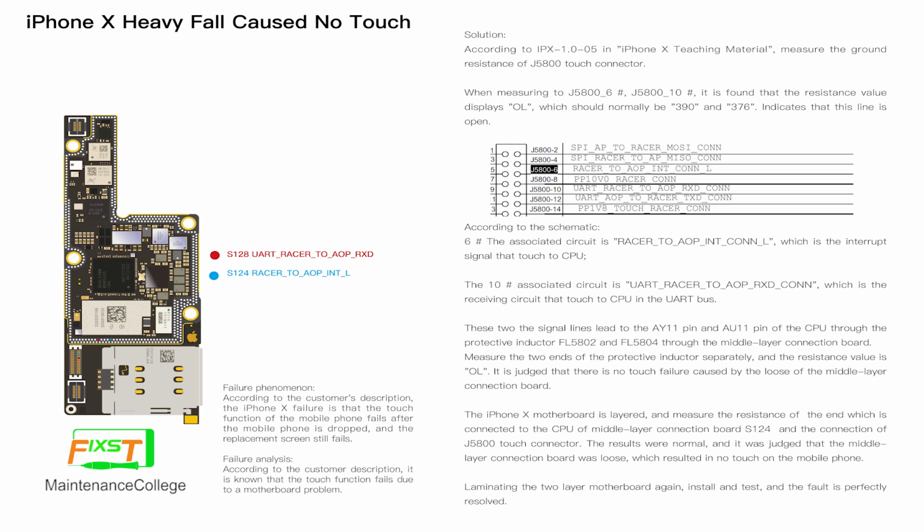Through the series inductors FL5802 and FL5804, through to the middle layer, the connection board. When we test these two inductors, the resistance is OL. It means that the touch problem is caused by a loose middle layer connection board, those two pins.